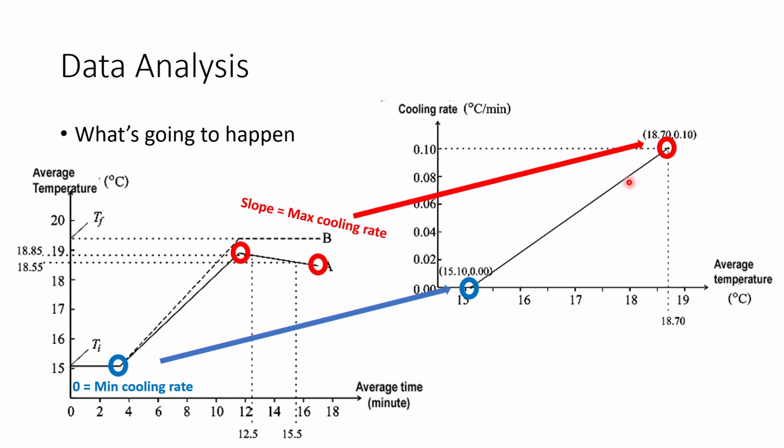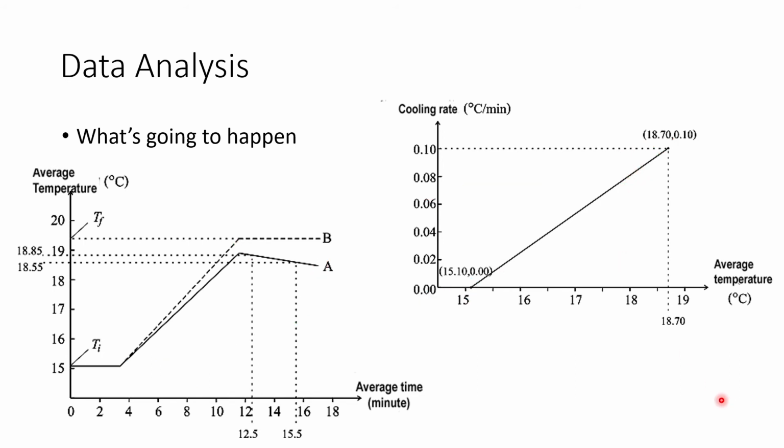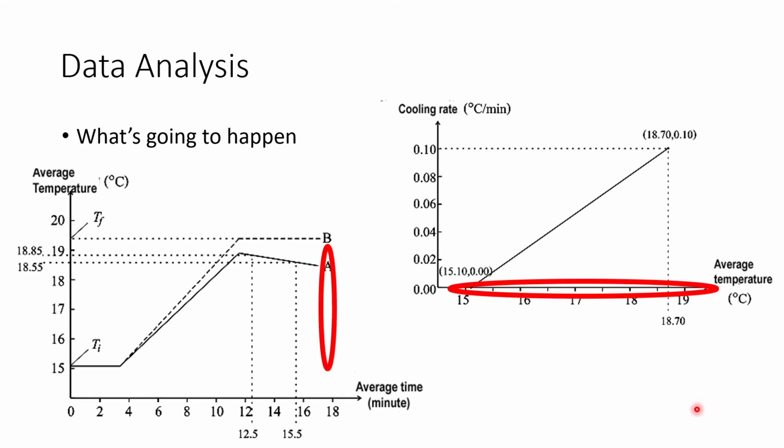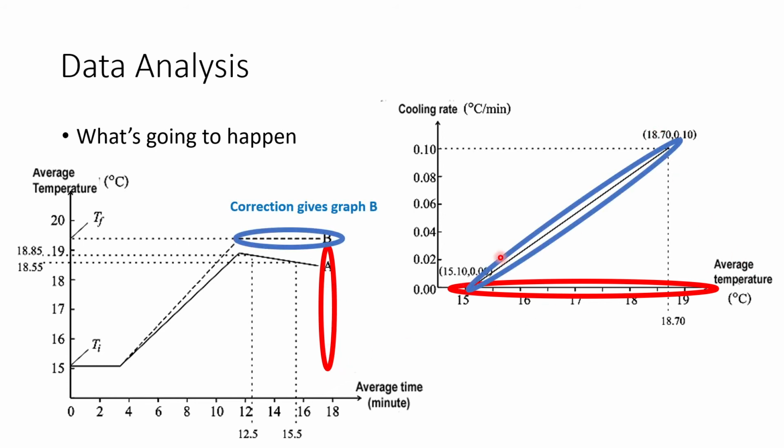After you have connected the line, you need to read the cooling rate at different temperatures and record the different cooling rates here. This cooling rate is going to be used to correct for the temperature that you've lost from the cooling effect. All right, so here we need to estimate the cooling rate for each different temperature.